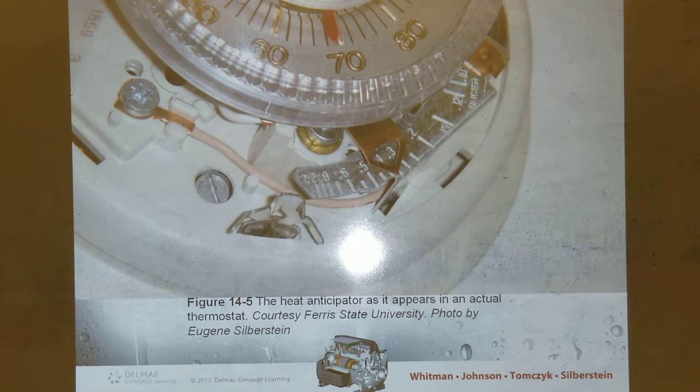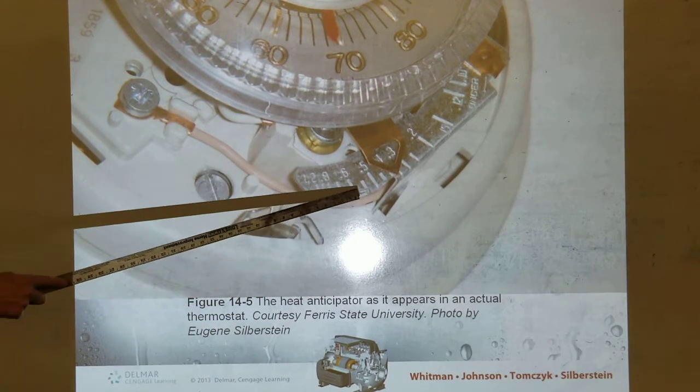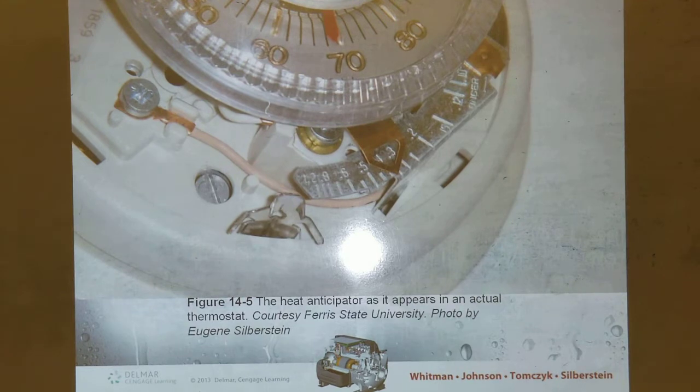So if you turn the heater off and you allow the heater to go through its cycle, once it turns off, the blower continues to run to take the heat out of the ductwork and out of the air conditioner, out of the heater and stuff. Well, all that additional heat gets pumped into the room, causing the temperature to go up past the set point. So this actually allows it to shut off a little bit early and allow that set point to come up when the blower finally stops. Pretty fascinating, really, when you think about it.